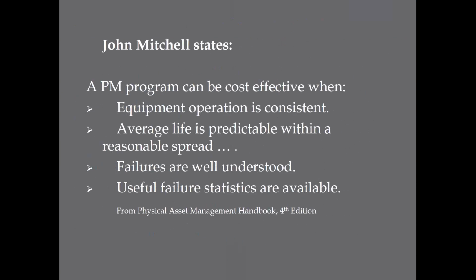Now, John Mitchell wrote this book, Physical Asset Management Handbook. It says a PM can be cost effective when equipment operation is consistent, which means you can't operate the equipment two days or 5 days a month and develop an effective PM. Your average life is predictable within some reasonable spread, understanding what the life of the component is you're checking.